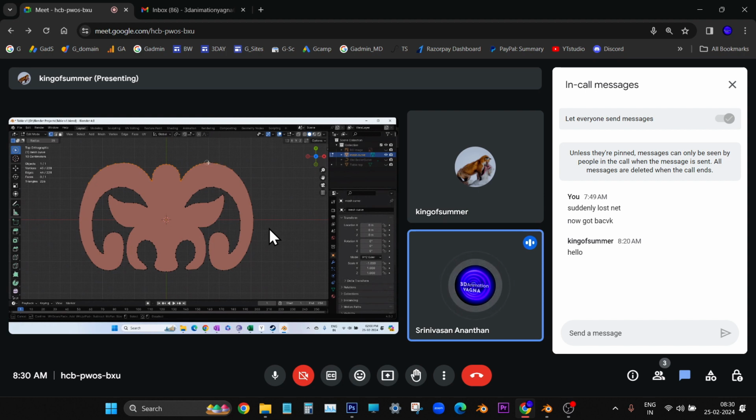Some vertices you didn't select. Careful. Yeah, come. One more vertex you have to select. Yeah. So this one, now press Alt E, extrude edges, escape. Now move option, move handle, and call it translation handle.